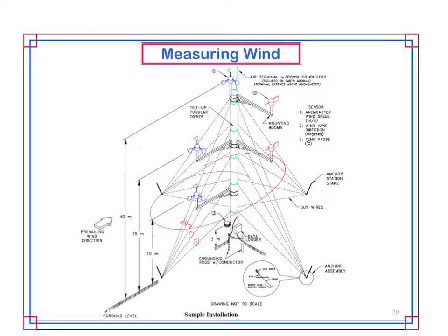And literally the way that you straighten the tower up, because when it goes up it looks like a snake, it's all crooked, is you will have a person tighten this location on this guy wire, loosen it over here, and it's just like a puzzle to figure out how to get the tower straight, but it only takes a few hours with a good crew to get it erected.